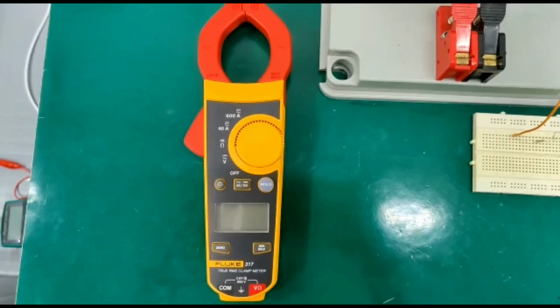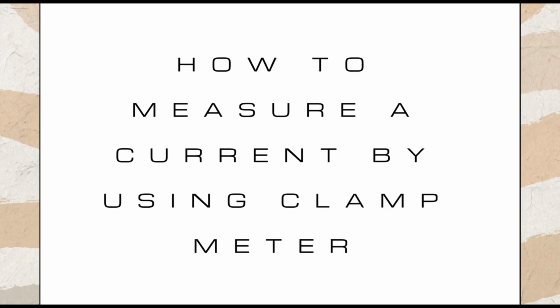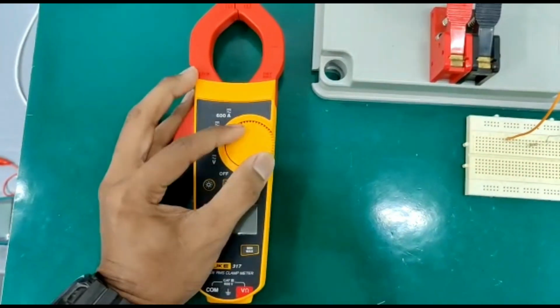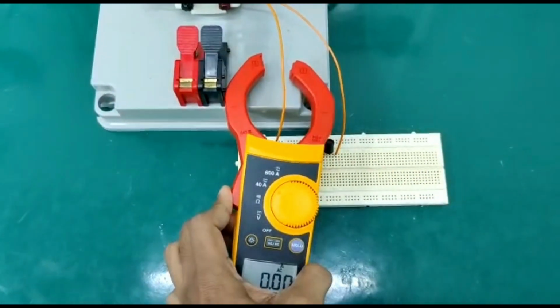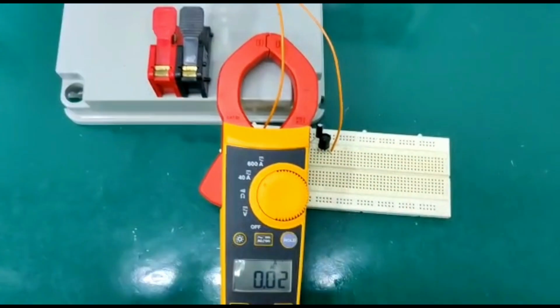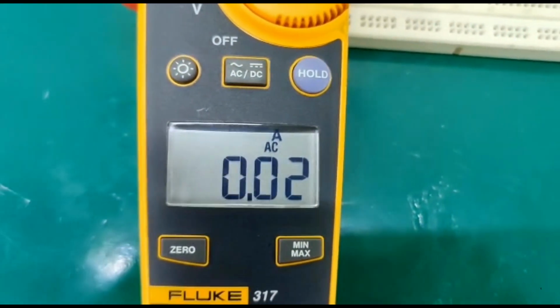For measuring current, we use a clamp meter because in this circuit we use an AC supply, alternating current. First, we have to rotate the selector to the 40 amp range. Next, we push the button on the side of the meter and clamp the input wire on the circuit. After clamping the wire, the reading will appear on the LCD.